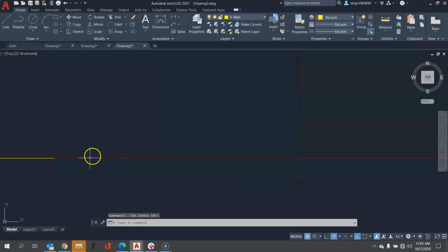So I'm going to say OK, and now you will see if I start drawing a line when I type in L, and my OSNAP, which is at the bottom of the screen here, is now selected, but you can also have it on by pressing F3. When I come closer, there's this green square with a tag endpoint that shows, which means if I'm here, I will definitely pick an endpoint of the line.